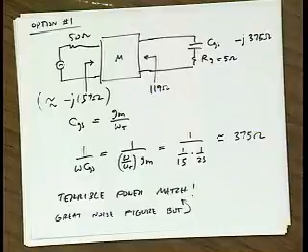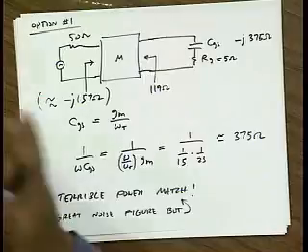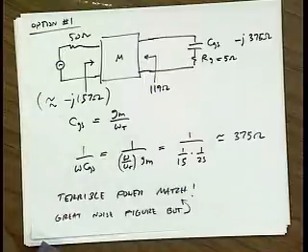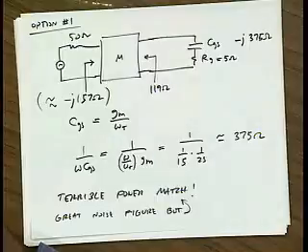Questions? Comments? Yes. Also, do you have to burn more current to achieve that noise figure, so your power? Well, we already said we're going to burn 4 milliamps. That's fine. That's a really good noise figure, right? If you could get that for 4 milliamps, you'd be pretty happy. It's not very power efficient. Yeah, if you take the power gain into account, it's terrible. That's the problem.